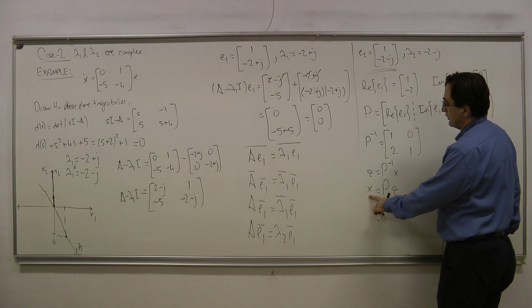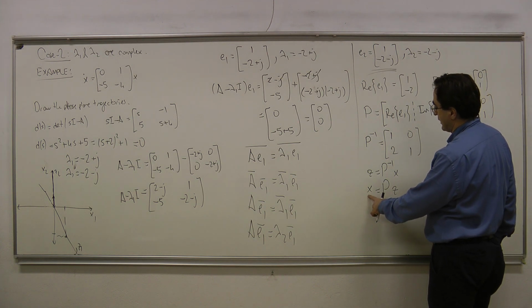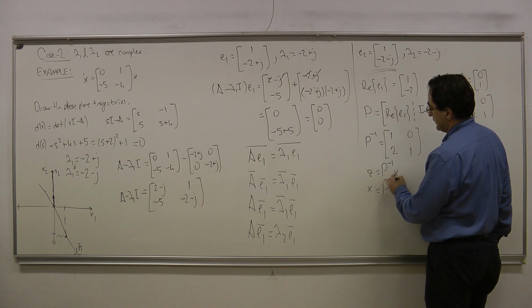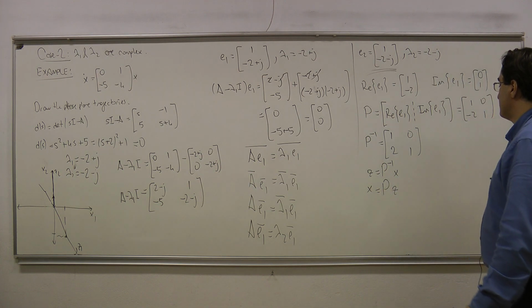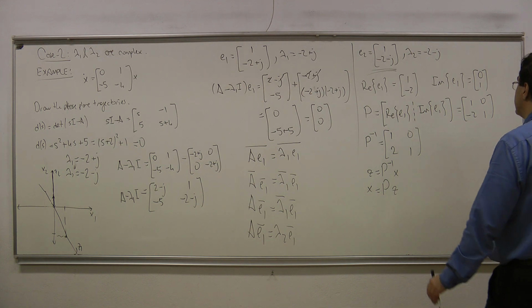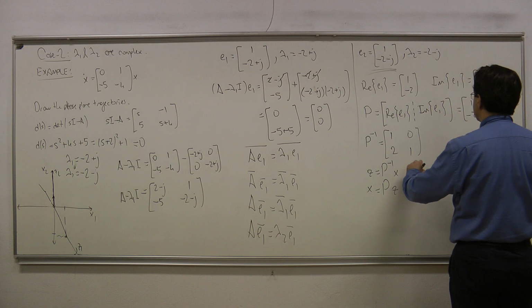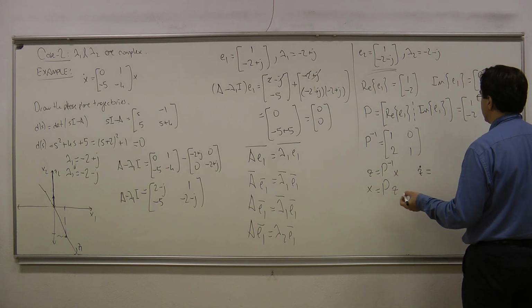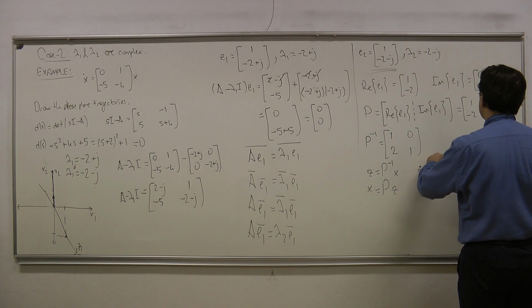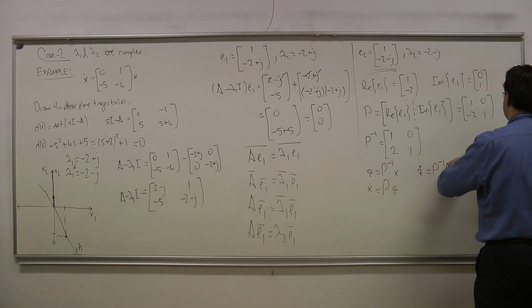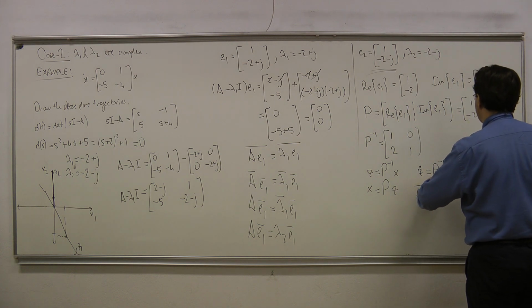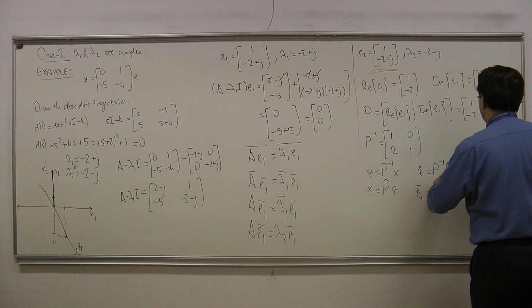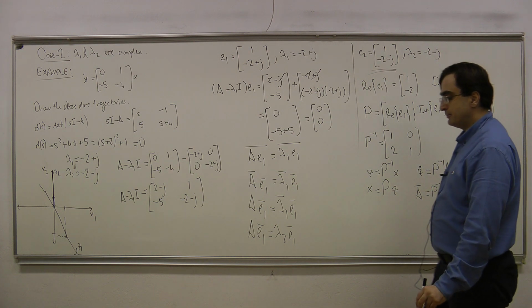So what we are trying to do is to write any x vector in terms of the columns of P. This equation tells me that, and here you see the inverse relationship. Okay. We know that such a state variable vector change gives us the following system. Since I have already done this a couple of times now, I can write this directly. P inverse AP Z, and that is A bar times Z. So our A bar, our new A matrix, is going to be P inverse AP.